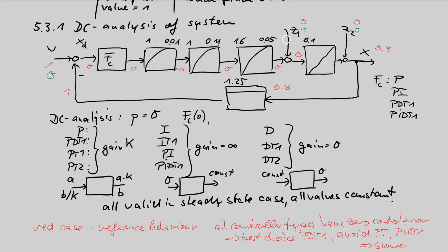So now a unit step response comes and we want to calculate the final value of the unit step response on C1, the disturbance step response's final value. What happens if there is a 1? Unchanged is this 0, because this is a fundamental physical law that if the output of an integrating block is constant, the input must be 0.